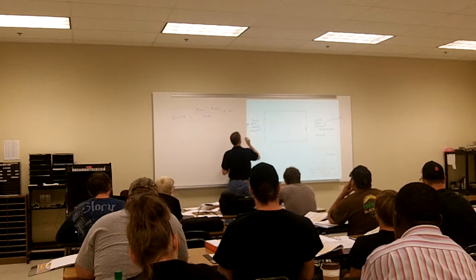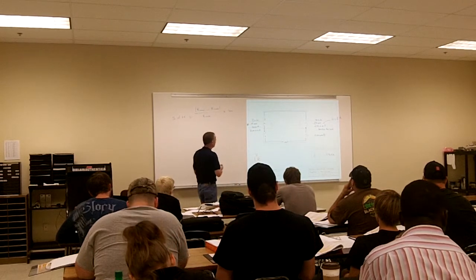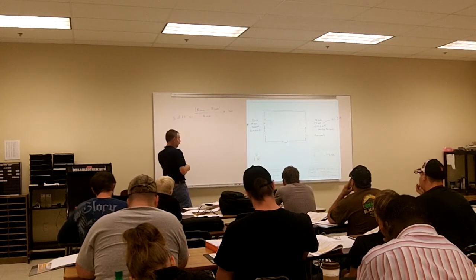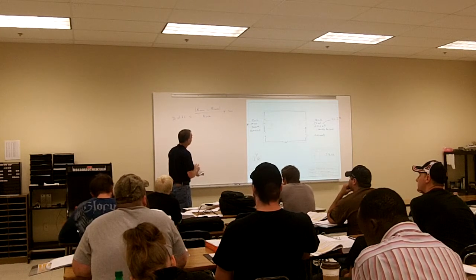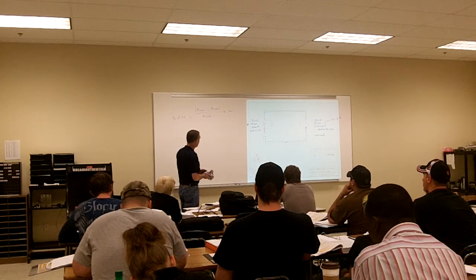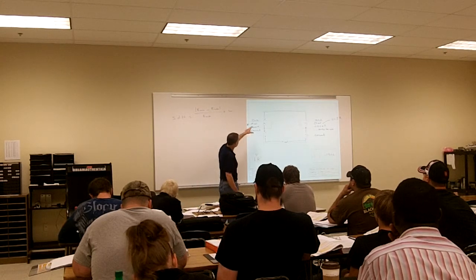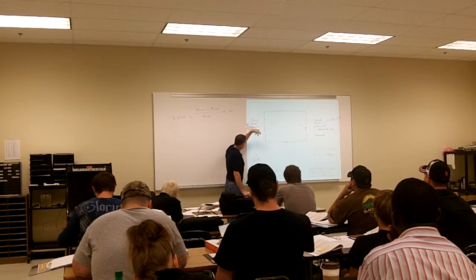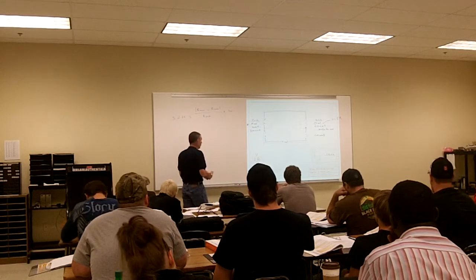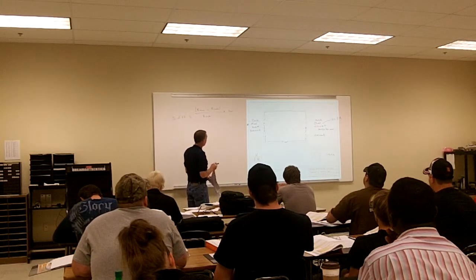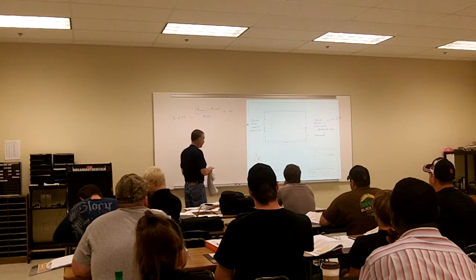Yep, we're good there. I have my voltage source. Yep, so we got our power supply turned on. Got the 24 volts going across it, but I still don't have anything going across my load there. So what would be my next thing I'd want to check out? Yeah, fuse would be a good thing.